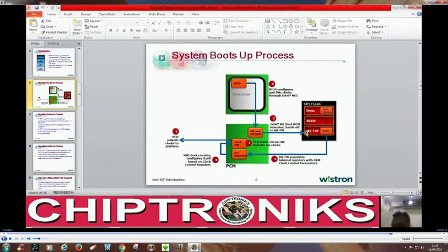It will read the AV from there, and the clock is loaded in the internal clock controller register. What does ICC stand for? Internal clock controller register. Then this data will be fed to the internal clock hardware of the PCH, and the PCH will output clocks to the platform.